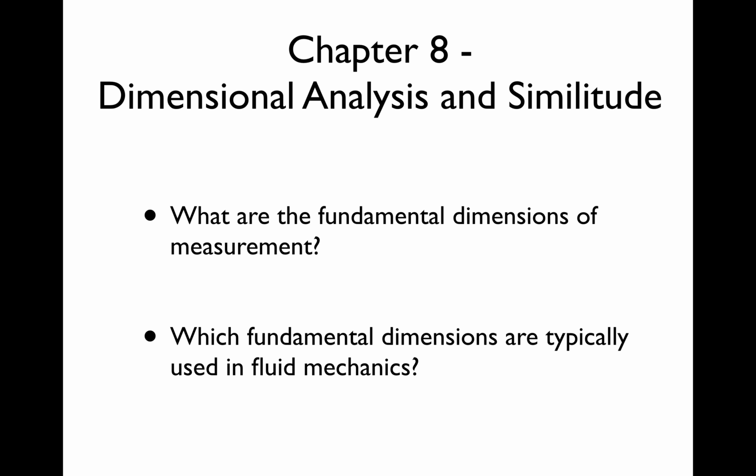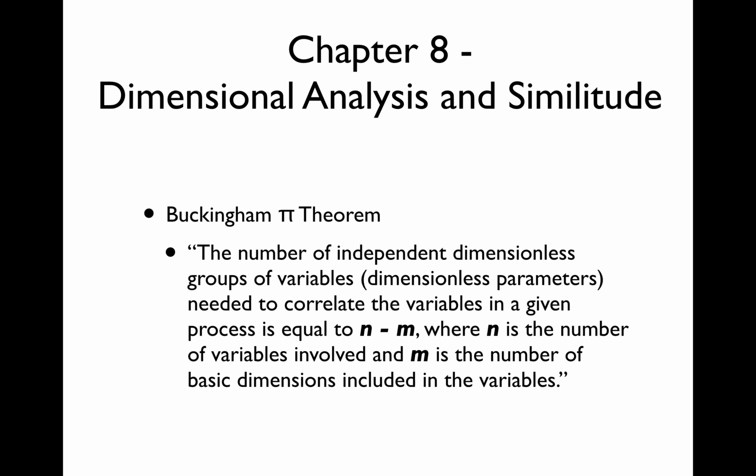So it's important in these problems to determine what the fundamental dimensions of measurement are, and which fundamental dimensions are typically used in fluid mechanics. And for our purposes, we're only having to deal with mass, length, and time. And so when we realize this, we can move on to the Buckingham pi theorem, and we can determine the number of dimensionless pi groups that are going to come out of any given analysis.